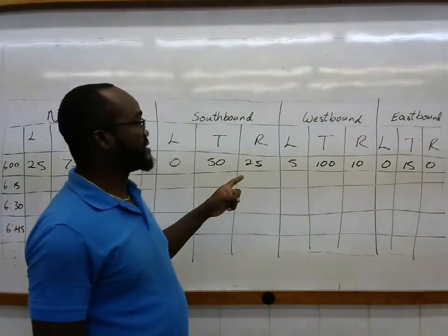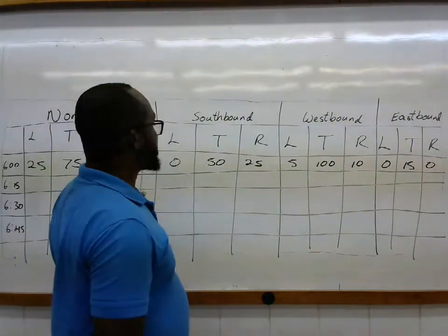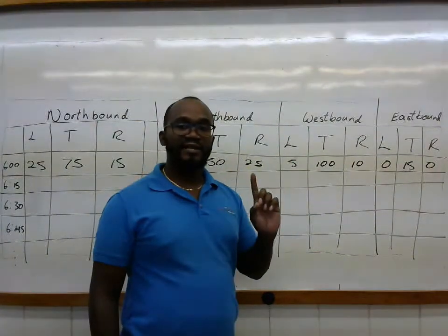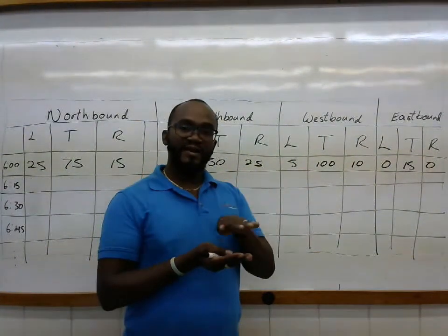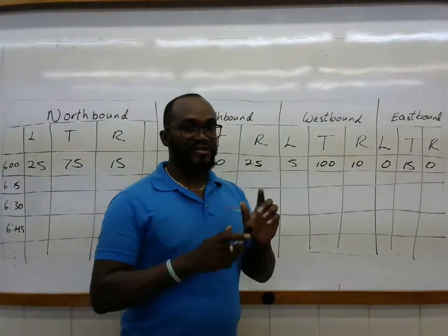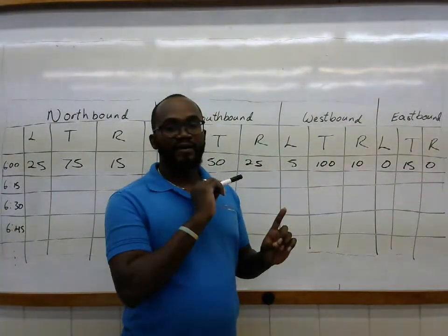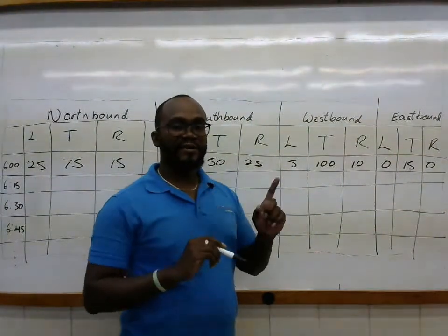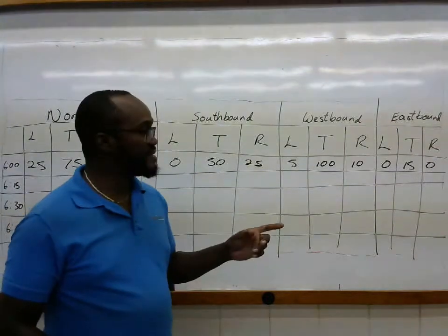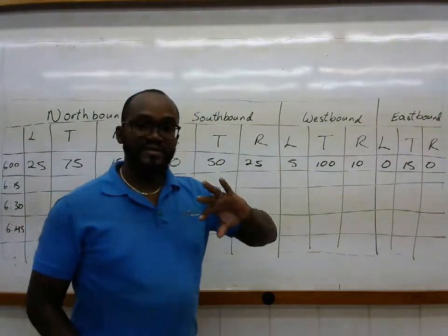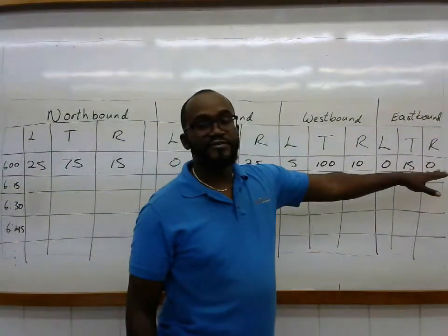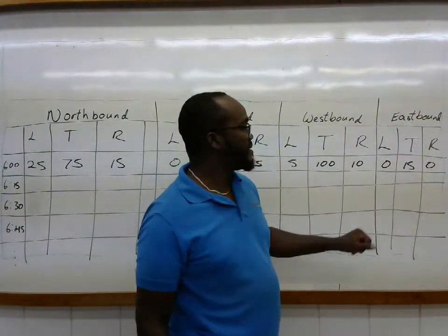Why is that important? Well, the volume is computed across all the classes. So you have to combine the 6 classes, excluding the pedestrians, because the pedestrians will not be in the direction of the traffic flow, but they will be perpendicular, as you would have seen in the field. So you sum those tables, and then you sum horizontally. Okay?